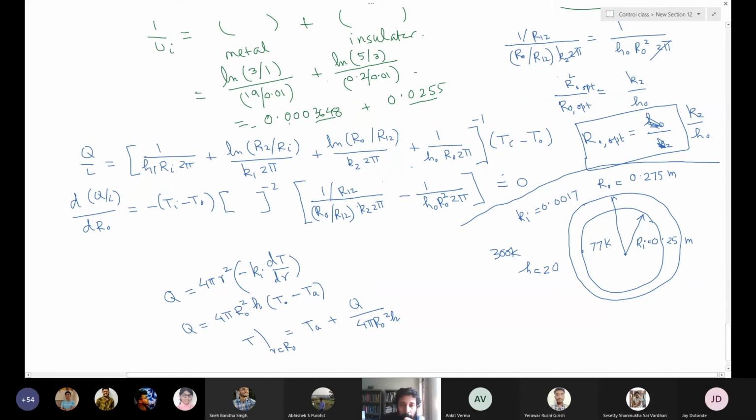Okay, that is because the heat flux direction is opposite. So in Newton's law of cooling, I have to put a negative sign here, otherwise it will give unrealistic things. When I write H into (To minus TA), this temperature is lower than that temperature. I am talking about r direction heat flux, so if I am talking about the negative r direction heat flux at the surface, I have to put a negative sign. Then it will be consistent. That's Newton's law of cooling, we have to put an appropriate sign.